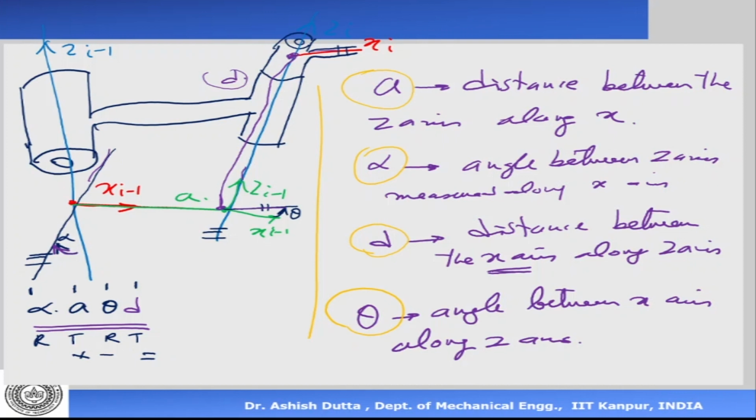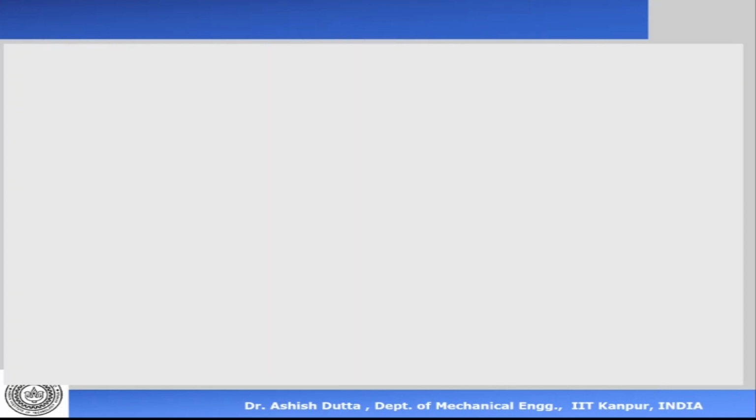So what you do is you write down the rotation matrix for this, write down the translation matrix for this and this, multiply them all out, and we'll get the generalized matrix, which will generate anything to an n plus 1 matrix. And that matrix has this structure. Let me write it down. So the generalized matrix T i minus 1 to i is given by